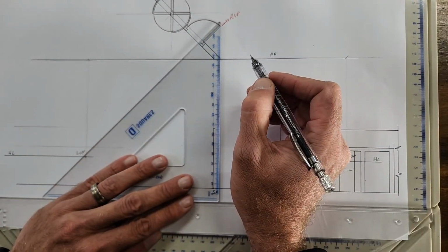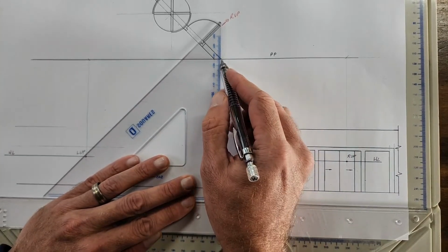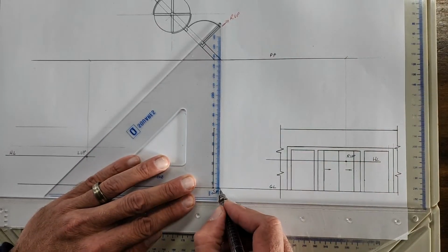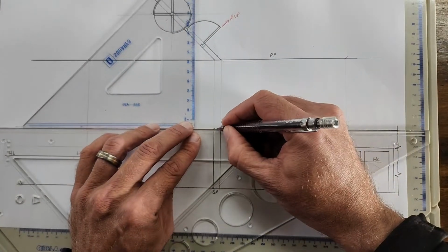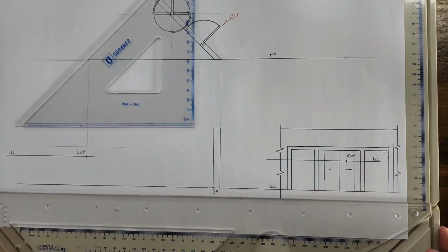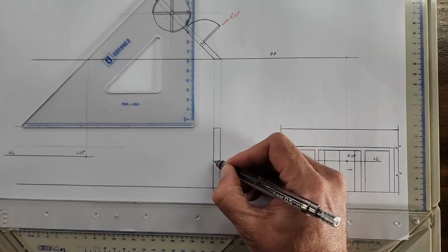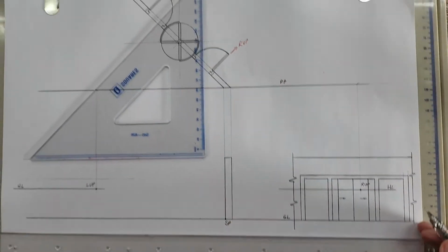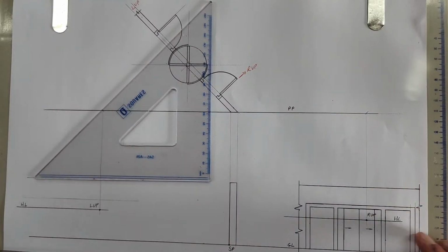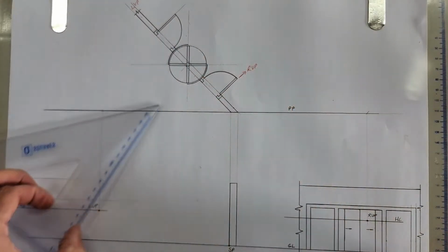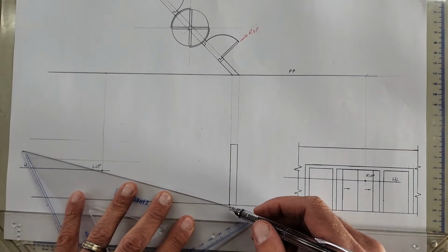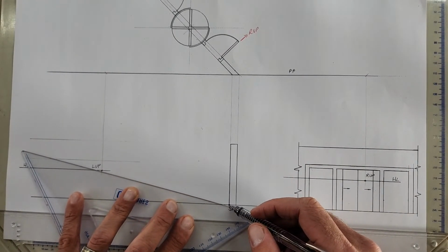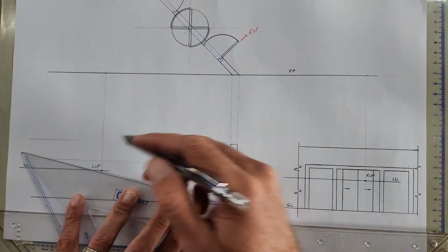I can bring that one also down, directly down, because we know it's touching the picture plane, so it will be on the ground line. It's going to be the same height. You can draw that in. Okay? That's actually almost a section that I'm seeing here of my wall. Alright? Then it goes in the direction of the left vanishing point. So to the left.